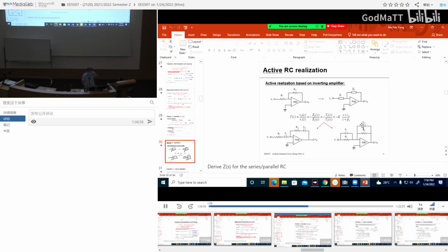Okay, so now we talk about another type of filter. This is a filter which we derive from the inverting amplifier that we analyzed previously, with R1, R2. Now if we don't use resistors and we say we are using some sort of impedances Z1, Z2, the analysis is still the same. The transfer function, instead of R2 over R1, becomes Z2 over Z1.